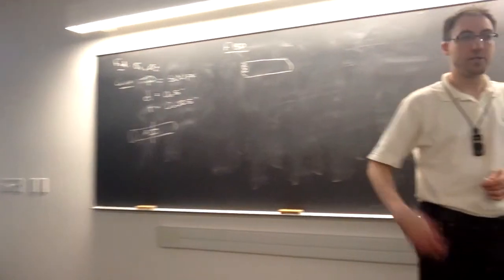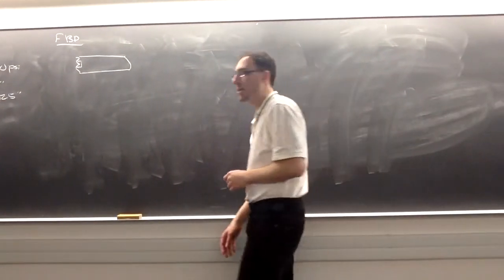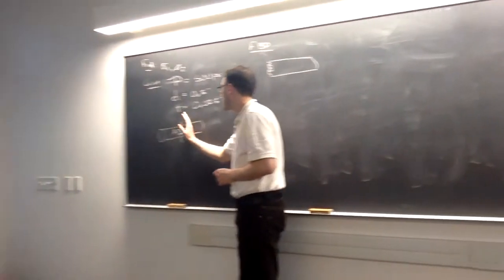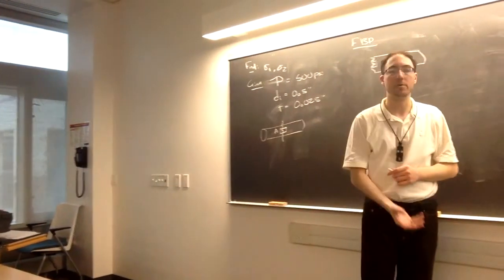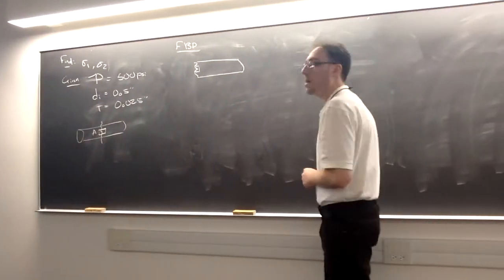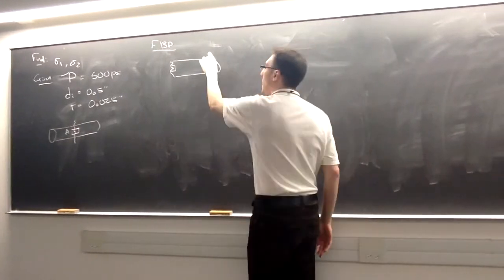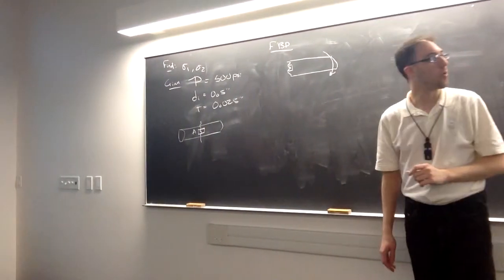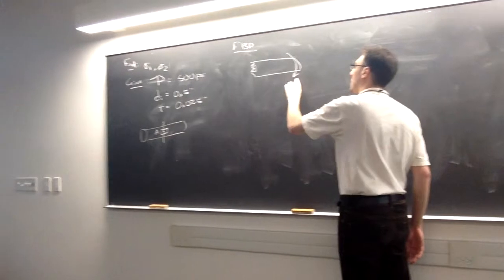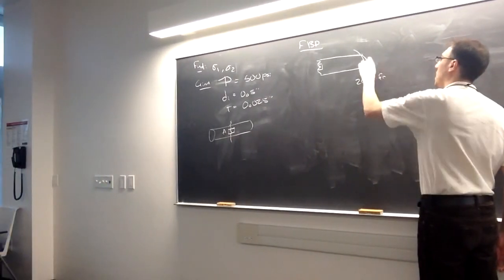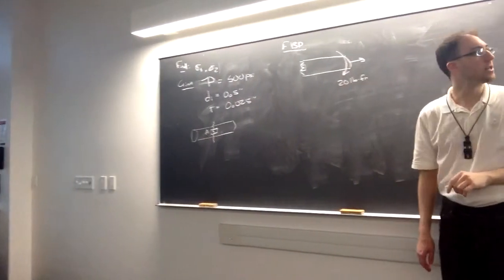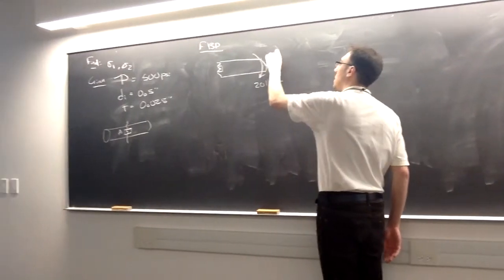Right, so cutting it just for this, I'm cutting it through the middle, but it doesn't matter if I'm in the middle or somewhere to the other side of it. The loads inside are going to be the same. So on my right-hand side, I'm applying this external torque of 20 pound-feet, and an axial load of 200 pounds.